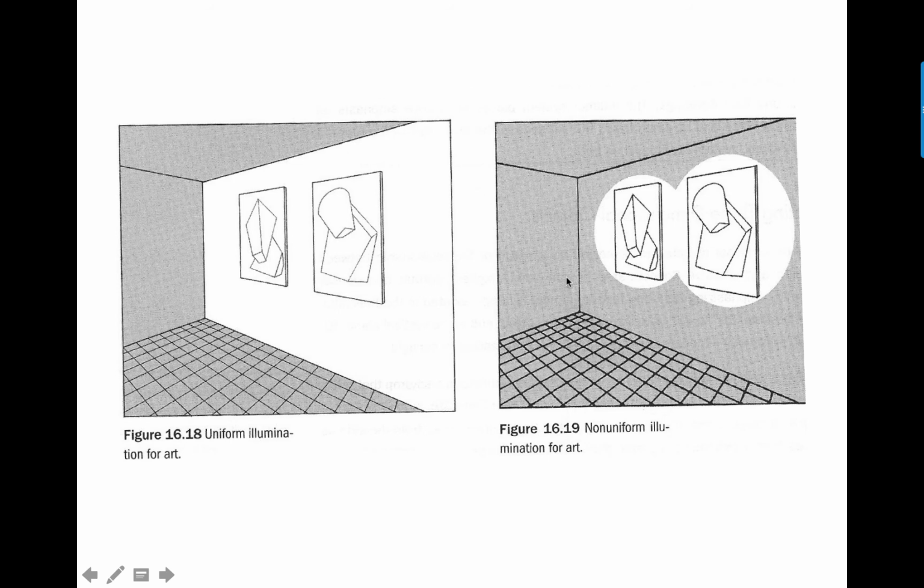And again, we've talked about this a couple of times. Your choice of how you want to light different things, these are paintings. You can have non-uniform illumination, and that can be quite dramatic, and you can achieve that with any type of light source, or you can go with uniform illumination, and again, that's typically a wall washer, but there are many flavors. That's a design decision, but for your choice of luminaire, you absolutely have to make sure that the light distribution is what you're looking at first, and then try to find a luminaire that matches the aesthetics of the space. There's not a whole lot of aesthetics going on in either of these spaces.